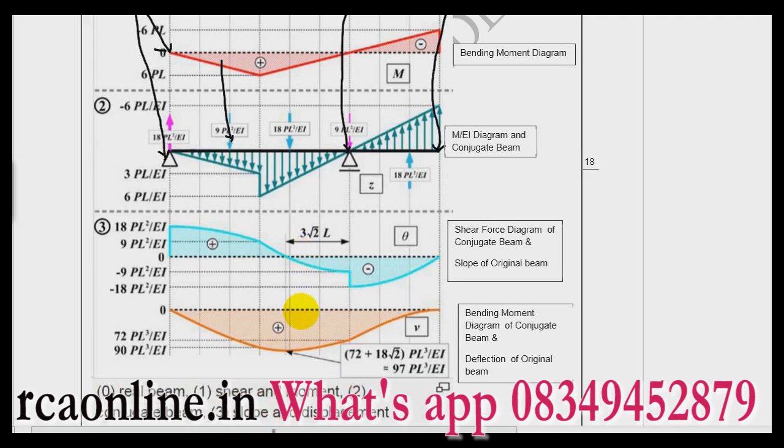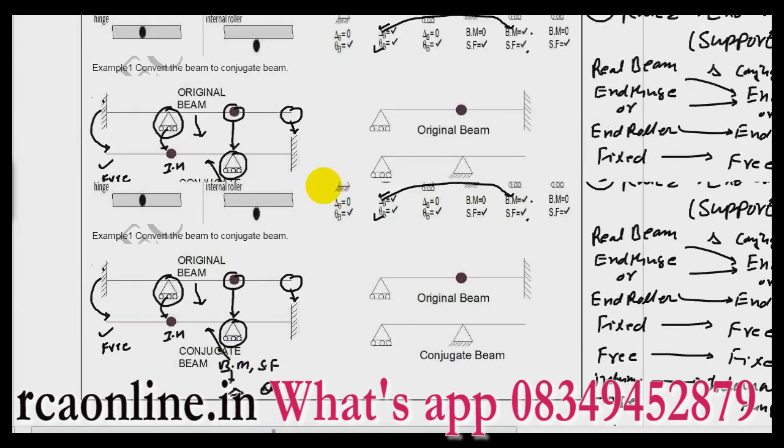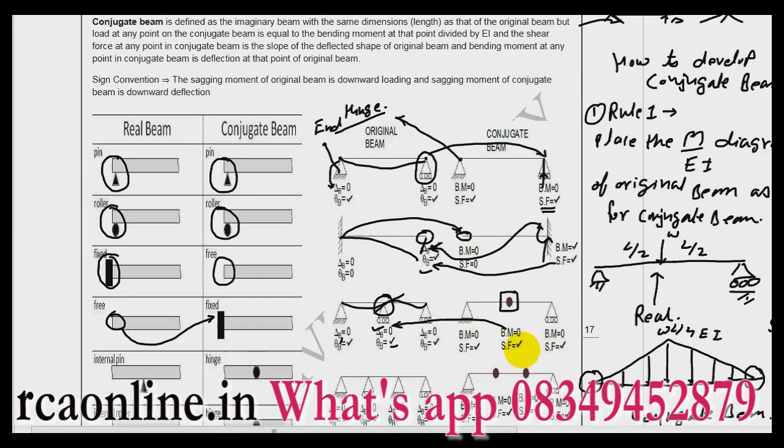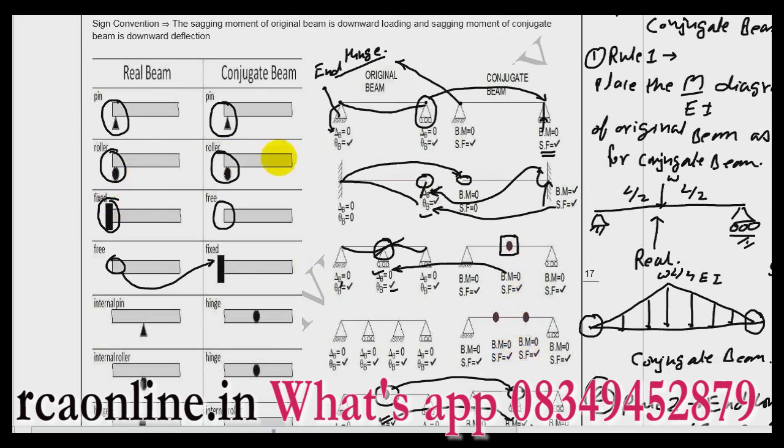Now for this conjugate beam, I will draw the shear force diagram again and the bending moment diagram. This bending moment diagram will give me the deflection of the original beam. So how lengthy is it? You have to solve a beam twice. So in objective, Castigliano's theorem and the area moment method are important, rather than solving the question for a conjugate beam. What they mostly ask is the concept and this conversion of original beam to conjugate beam. So you have to concentrate on the conversion only, how to convert a real beam to a conjugate beam.